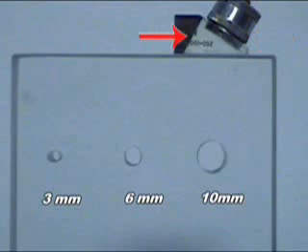A refracting wedge is used to provide a shear wave beam, nominally refracted at about 55 degrees from the normal. The beam was directed at the 6 mm diameter hole, and the delay increased to 3.8 microseconds after the element has been pulsed. The mechanical pulse enters the glass from the wedge. The incident angle is greater than the first critical angle, so only a shear mode is present in the glass.